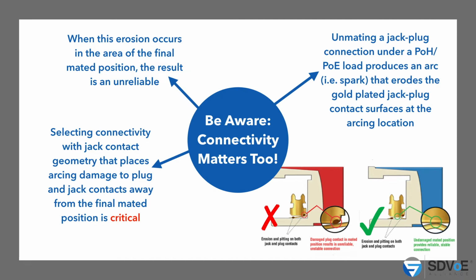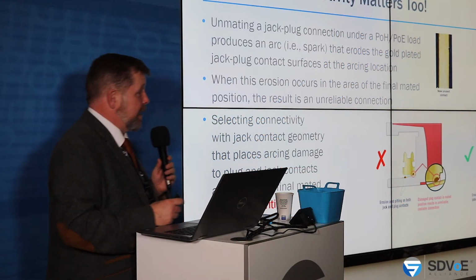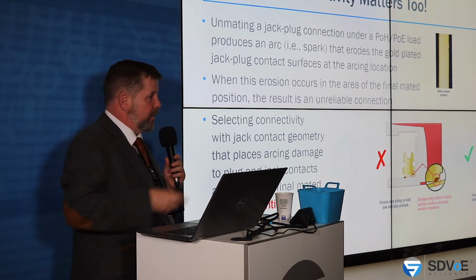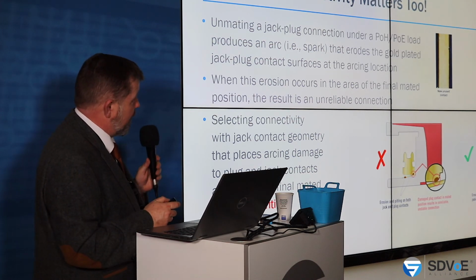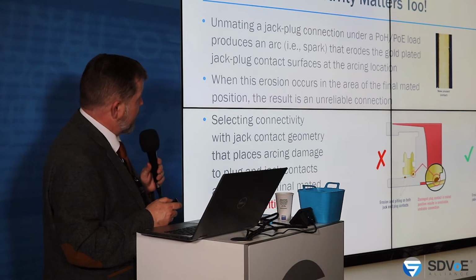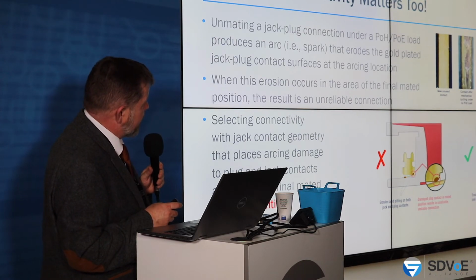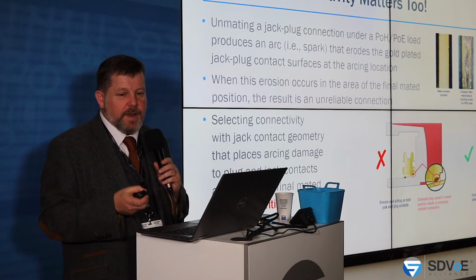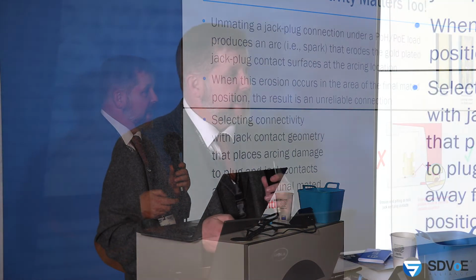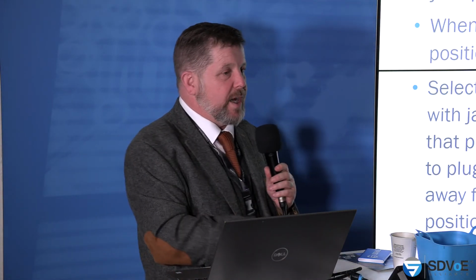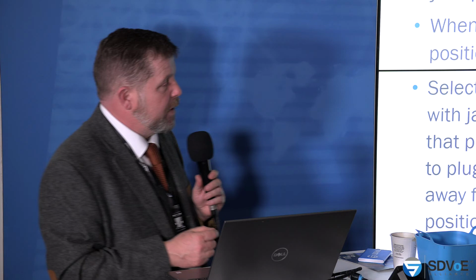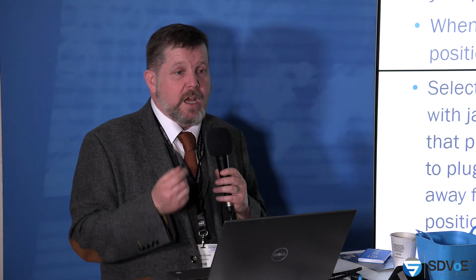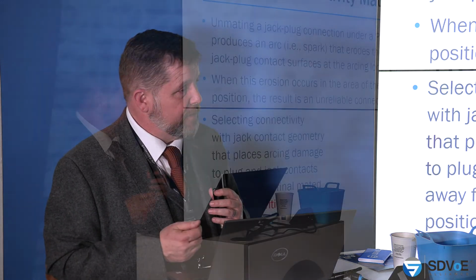So just to show you, just coming up here, this is a connector. It's just a blade that you plug into any device, and that's one of those 8 pins on an RJ45 that you plug in. Absolutely no damage. It's newly there, nothing been done to it. This is a conductor that's literally working with power over Ethernet now, and we've got those two connections working together. And then if I start literally unplugging those RJ45s, what do we risk? We run the risk of an electrical arc. And that electrical arc will start to damage the quality of your connections.